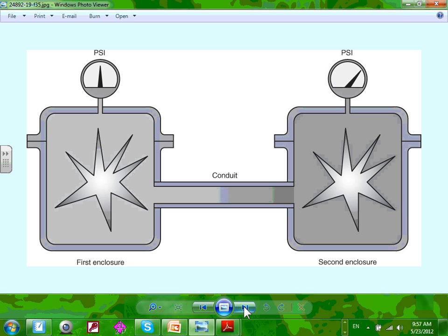So Chris, explosion-proof equipment number 1, I have an arc and spark, the gas got in, I have an explosion, right? Now that expanded gas will be channeled out through the conduit. You don't have an explosion here, seal here, and it goes all the way to the second one. And the explosion experts say that process creates a bigger explosion in the second enclosure that the enclosure most likely will not be able to handle.